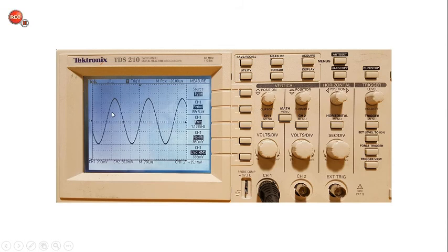We can determine the peak voltage. Here you see that the oscilloscope screen is divided into squares. Each square is 1 division, and each square is also divided up into smaller divisions. There's 5 altogether, so each small tick that makes up the square is worth 0.2 of a division. If you count the total vertical divisions, I'll start here at the nearest whole division.